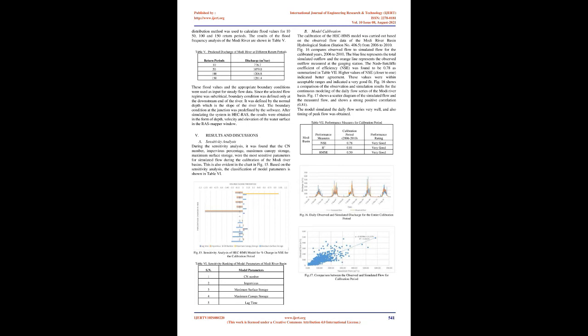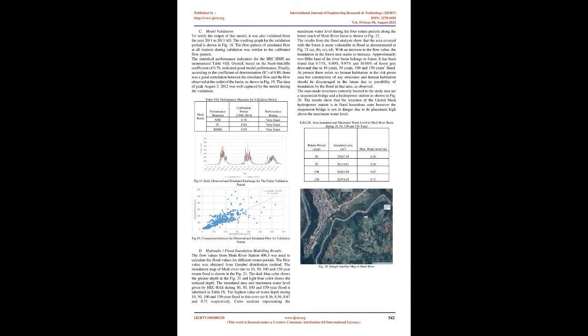The values of the parameters were estimated by observation and analysis of stream and basin characteristics in ArcGIS. Since some of the required parameters cannot be estimated precisely, the parameters were calibrated by systematic approach for the best fit of the observed and simulated stream flow. The validation of the optimized parameters was performed by running the prepared model using the same parameters used in the calibration period.